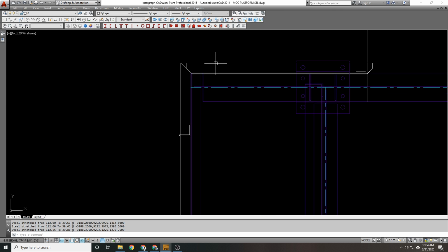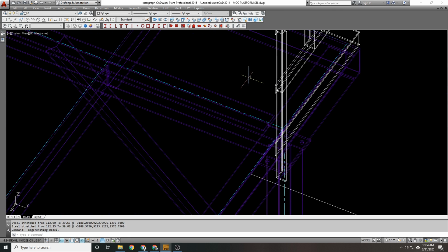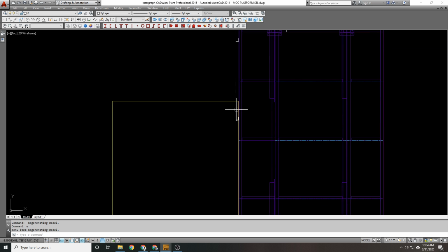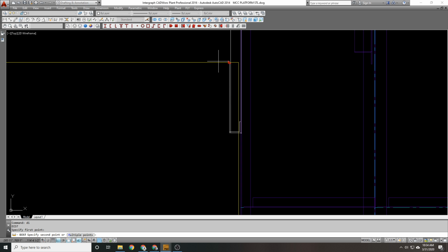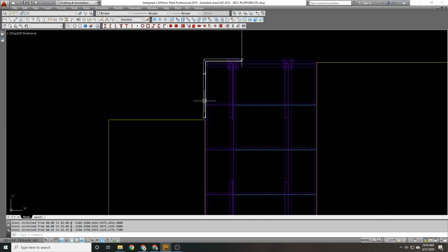They overhang because I had a previous miter. I'm going to remiter these, and actually I'm going to also take this, and let's see, what's the distance between here and this edge of this building? 1'4". So I'm going to bring this back 1'6". And that should cover this handrail.